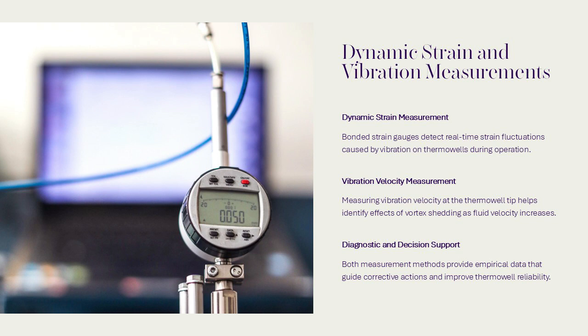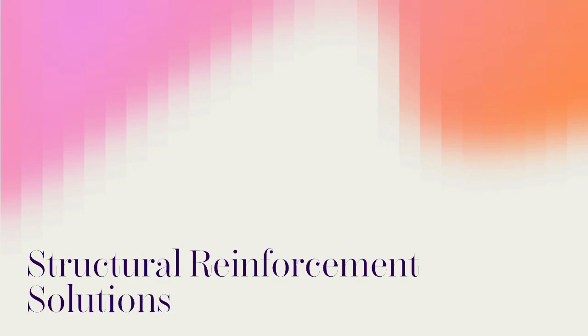Another advanced technique involves measuring vibration velocity at the thermowell tip through its internal bore, provided the bore diameter and temperature allow. This method helps confirm whether vortex shedding is exciting the thermowell as fluid velocity increases. Both techniques are diagnostic tools that support decision-making for corrective actions, ensuring that interventions are based on accurate, empirical data rather than assumptions. Velocity collars and welded gussets.